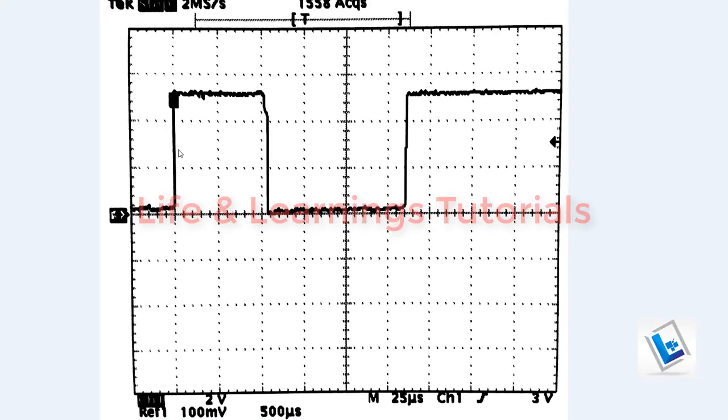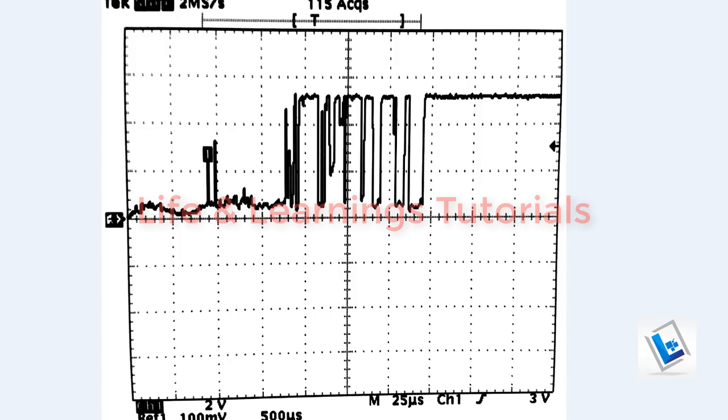We want sharp rising and sharp falling edges when we press and release the push button. This ideal waveform is very hard to achieve because when we press the push button, we will encounter this problem, which is also known as the bouncing effect. Before getting a perfect signal output from the push button, we will get multiple bouncing waves because of the mechanical contacts making and breaking. And these multiple signals can lead us to a false detection of the button press and release.